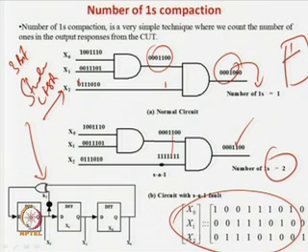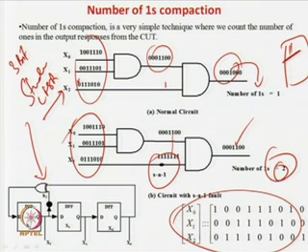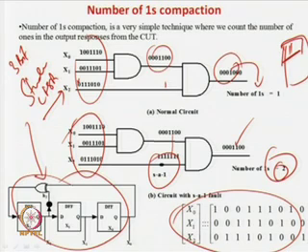Now, what happens if you apply this set of patterns? The ROM had stored 1, but the output response here is showing 2 ones. So, in this case you detect that there is a stuck-at-1 fault over here. The requirement is a single-bit ROM and a 3-bit LFSR, and it can test a stuck-at-1 fault here. Similarly, this set of patterns can test a series of other faults, which we can easily find out, by using a 1 bit ROM.